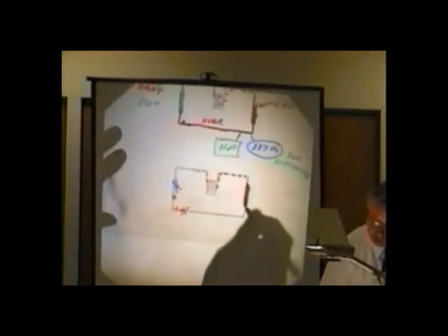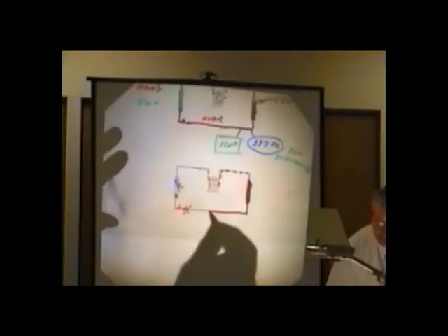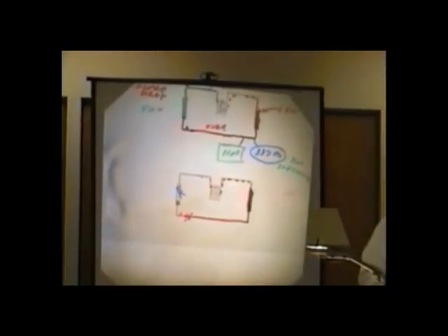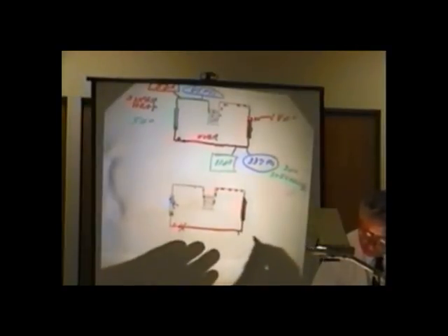So under those conditions, we got vapor, vapor, vapor, and whew, lots of liquid. Wow, it looks like that, doesn't it? We're stacking refrigerant because we have a 100% restriction. So we come down to here, and we come down to here, and that's as far as it goes. That's it. Now, let's go over here and put our pressure gauge on the high side, and put our pressure gauge on the low side, and of course the low side shows a vacuum with a 100% restriction. And we have the pressure gauge on the high side.